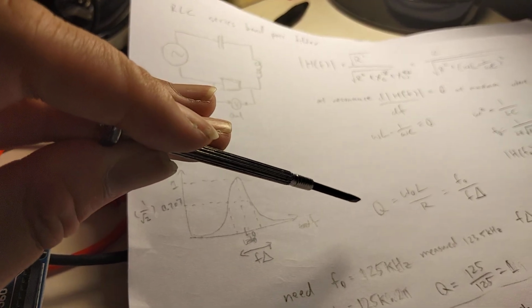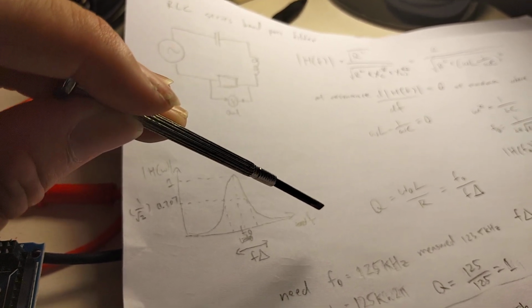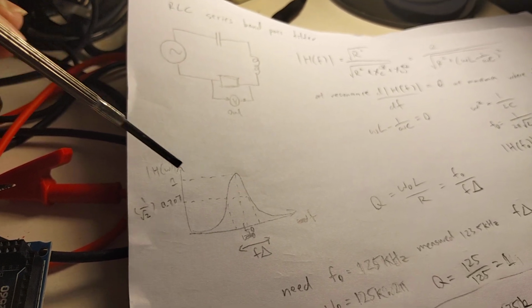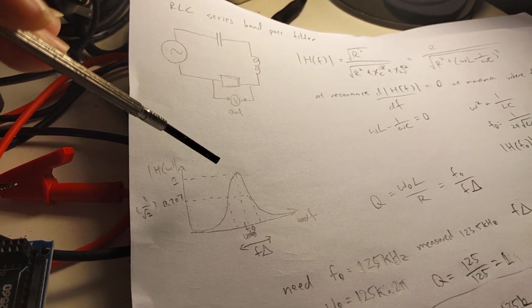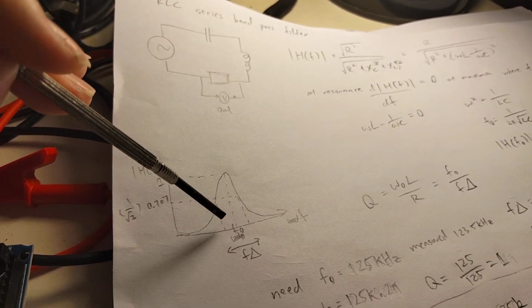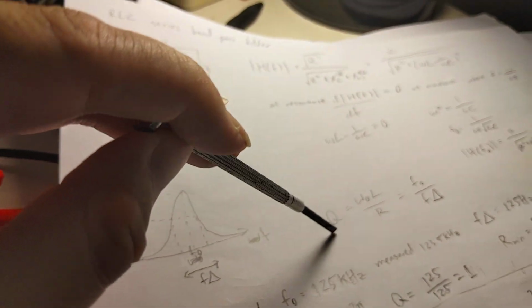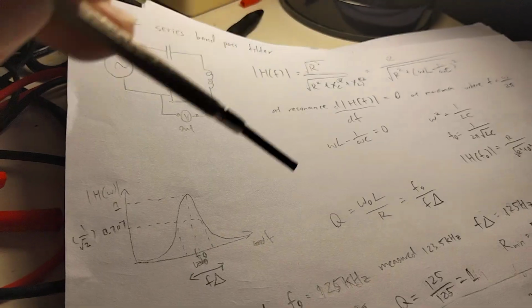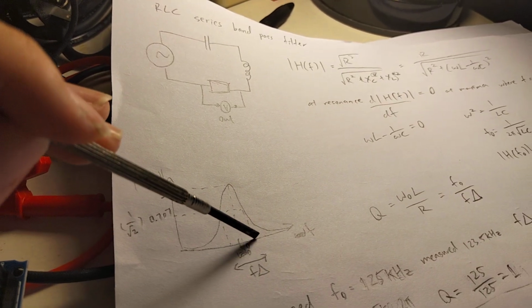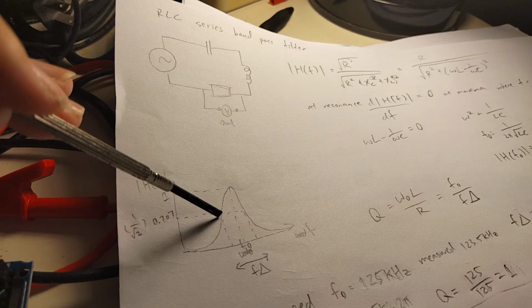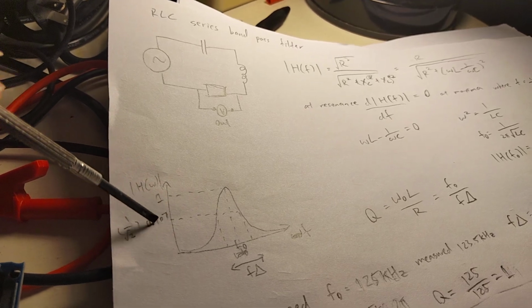Whereas if we had a low Q factor, in the decimals like 0.01 or something, it'll let pass frequencies that are pretty far away on either side of 10 hertz still. And the Q factor itself is a number determined by the resonant frequency divided by the range at which the signal was attenuated by 3 dB, which is 0.707.